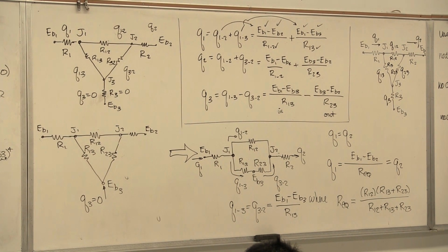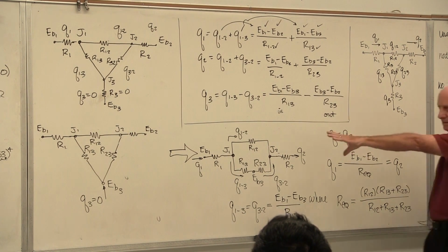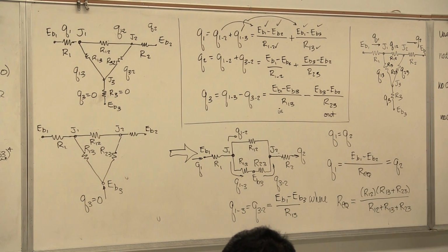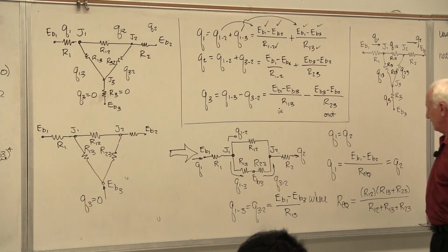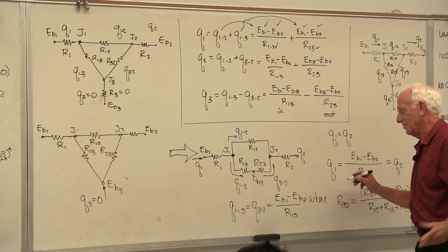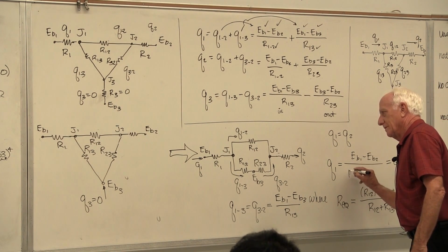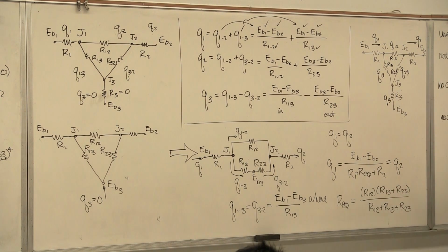But we're going to show you how you can also use the equations, besides looking at solving it with the graphical picture of what's going on, the thermal resistance network. You can do it by looking at this simple picture here and doing a series parallel circuit. All you've got is 2 more resistors here. We'll go ahead and do it. R1 plus this plus R2. There's the answer right now. That's all you do. Very simple. Series parallel.